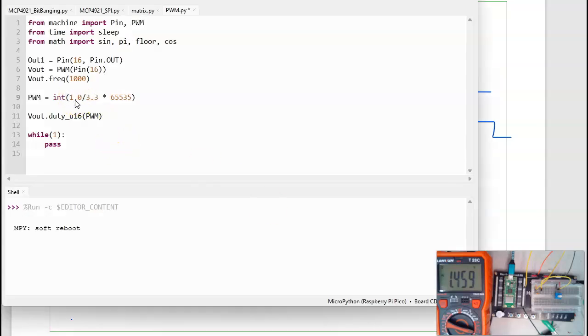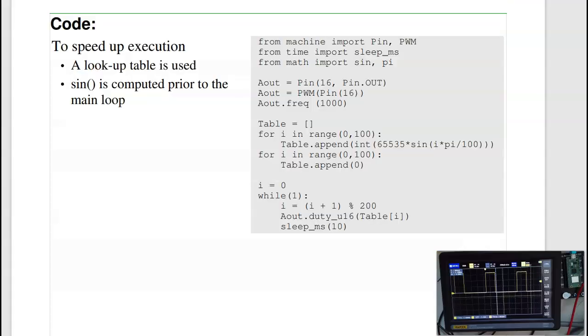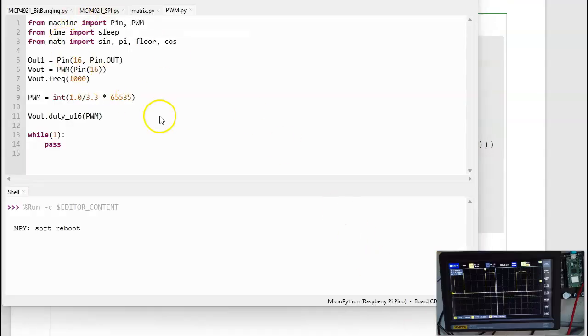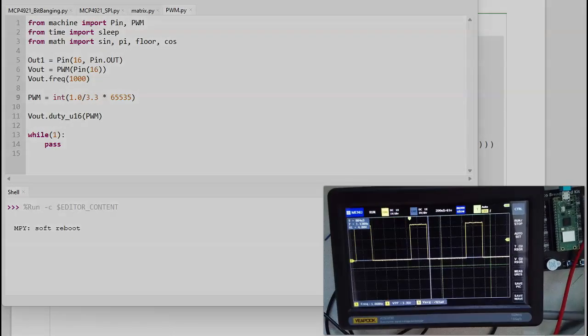As I change the duty cycle, the AC voltage, what I'm on right now, doesn't really change. That's because the peak-to-peak is always 3.3. 3.3 volts peak-to-peak has some RMS voltage. The AC voltage doesn't really tell you anything. Go back to DC voltage. That's the average. So to see what's happening, this is where oscilloscopes are really useful.